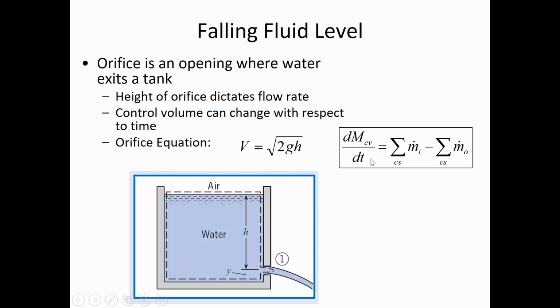So we're going to combine these two ideas together. And remember, the orifice equation originates from the Bernoulli equation. If we want to find the velocity of this jet that's coming out, we only have to compare the location here to the location of the water surface and apply Bernoulli's equation, because that'll allow us to account for how much pressure there is at that elevation, and that pressure goes from being potential energy into kinetic energy, and we've got the discharge out. So the orifice equation, as we talked about in lab, is derived from Bernoulli's, and so